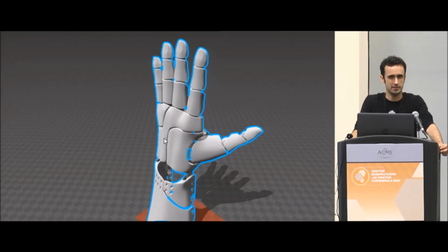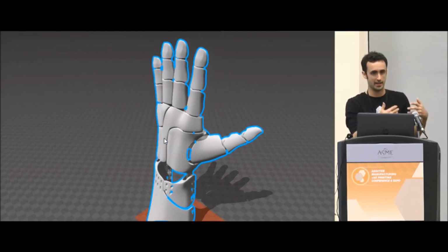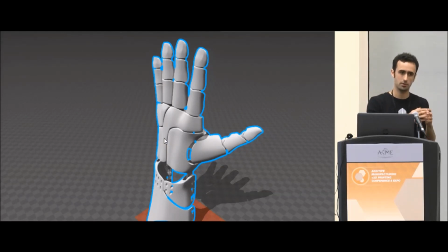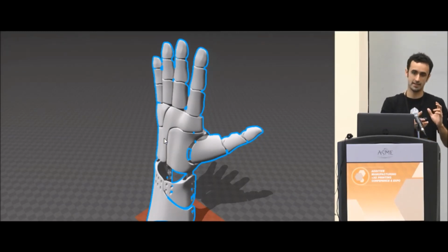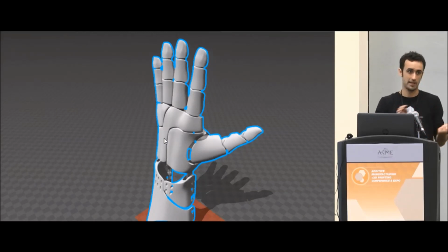There are also false positives you can get occasionally. So the more accurate your machine is, and SLA is fantastic for being super accurate. If you print it on an FDM printer and it fits together and screws really well, and everything works, and then all of a sudden you send your CAD files off to get injection molded, and they build you tools and send it back, and it doesn't fit. It's because your FDM prints probably aren't as accurate as the injection molding tooling is from your CAD package. So maybe it gives you a false positive that it does fit together and screws really well, or maybe it actually doesn't fit together, and it might actually work if you injection molded it, but the accuracies are off.